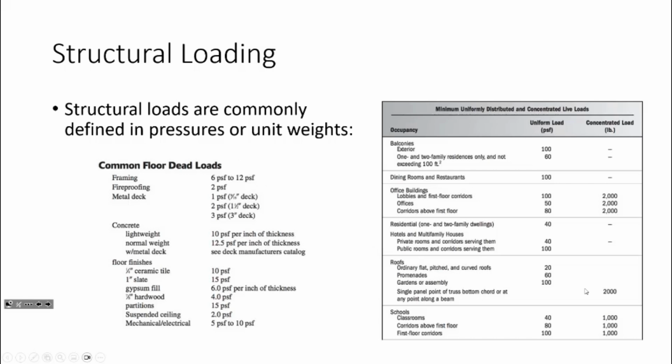fireproofing the metal deck. So if you've ever been in a commercial office building, or maybe if you go into the stairwell, you can actually see sort of the metal pan that serves as the formwork for the reinforced concrete, you know what I'm talking about? So we've got metal deck, concrete, whether it's lightweight, normal weight, what have you, floor finishes.